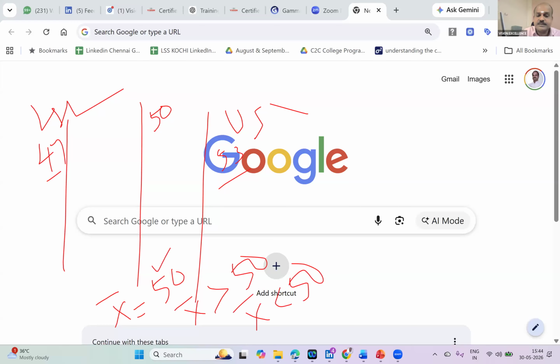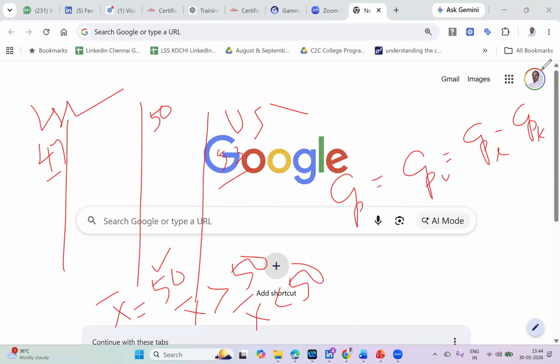Now tell me, let us take the first situation, first condition. Average is equal to target. Now, in this case, you just have to relate CP, CP upper, CP lower, and CPK. Now, what is the symbol I should use here? Equal. All of them will be equal. You don't have to calculate so many things to judge the capability. Calculate any one. Are you with me, all of you? Yes, sir. If there is no shift, CP will be equal to CP upper will be equal to CP lower will be equal to CPK. Calculate any one and that will be the thing.